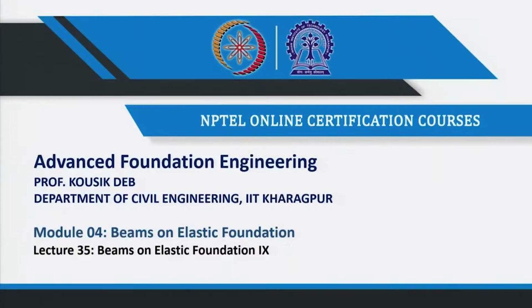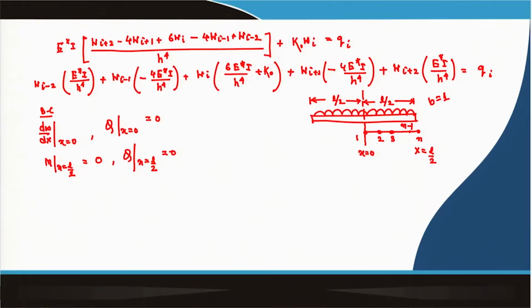So, last class I discussed how we can express this beam equation in finite difference form, and I was discussing the case when the beam is resting on Winkler springs and then how to use the boundary conditions. So, this was the expression. These expressions, which are expressed in central difference scheme, we have to apply at all the nodes.